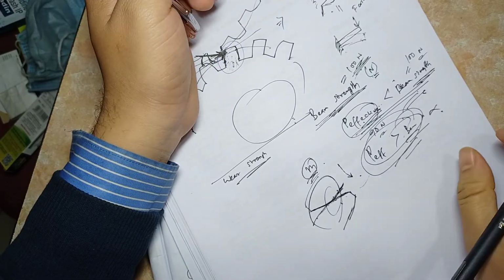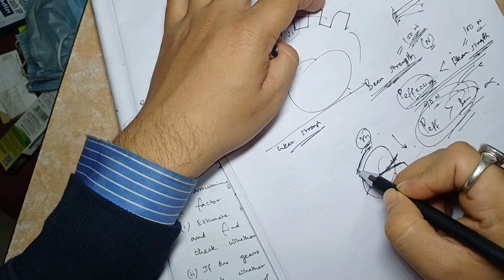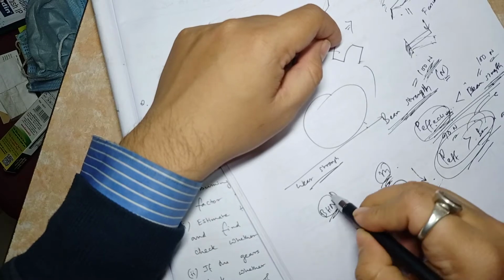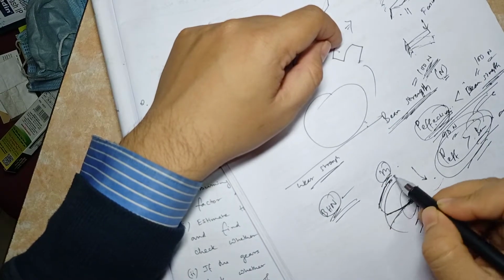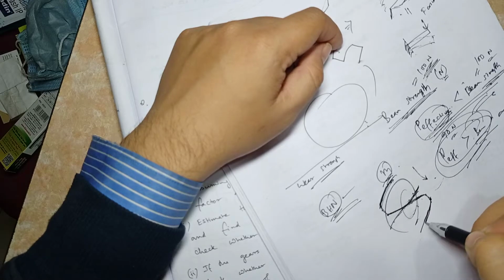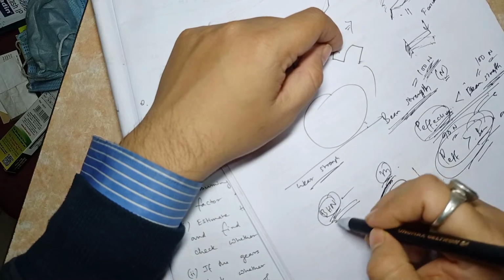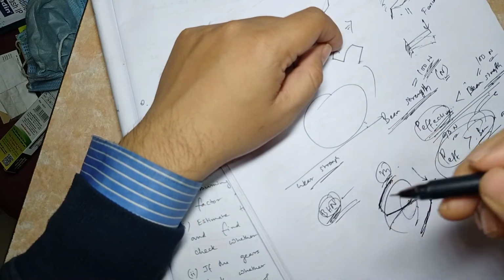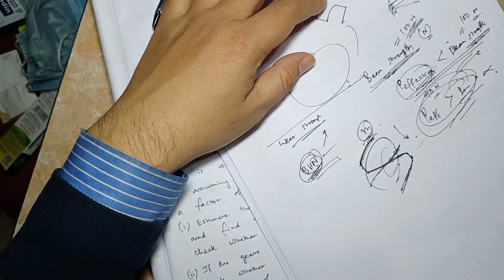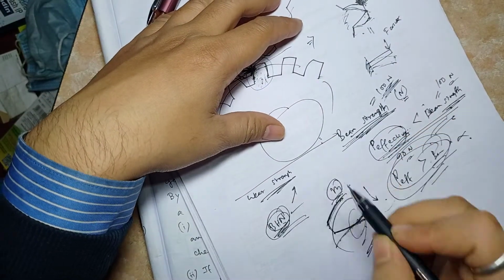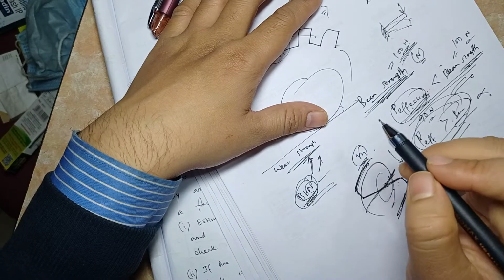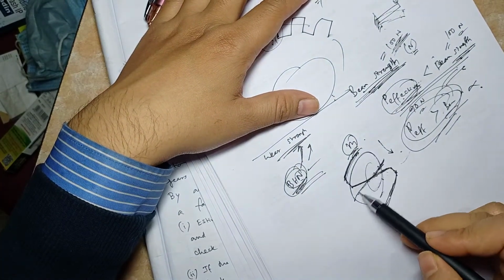So just to prevent that, we have to harden the surface of the gear. There we consider the Brinell hardness number. So we have to increase the Brinell hardness number. The higher the Brinell hardness number, the harder the surface of the gear. So Brinell hardness number is the criteria here for wear strength. We'll see how beam strength and wear strength are calculated. The higher Brinell number gives you higher wear strength, so it is resistant to wear.